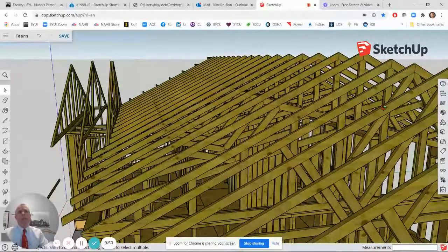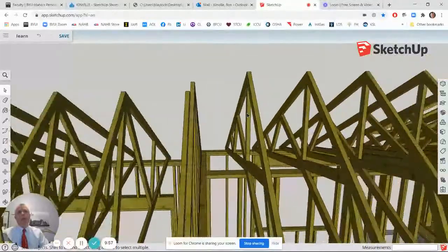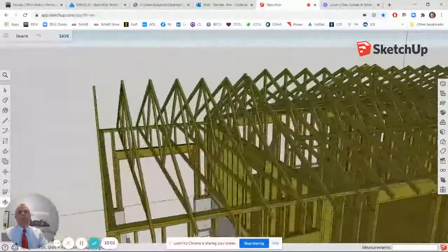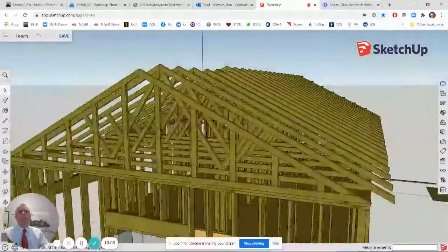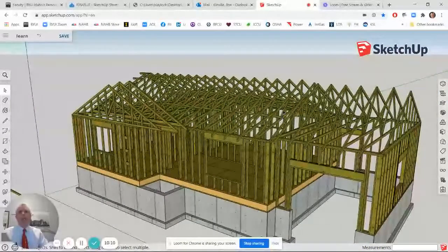On the back side, you're just going to have some ladder framing. Actually, we've got trusses, but we don't even need any ladder framing back there. That's going to work out just fine the way it is. Okay, so put in the rest of your lookouts and we'll be all ready to move to the next part of the roof framing.